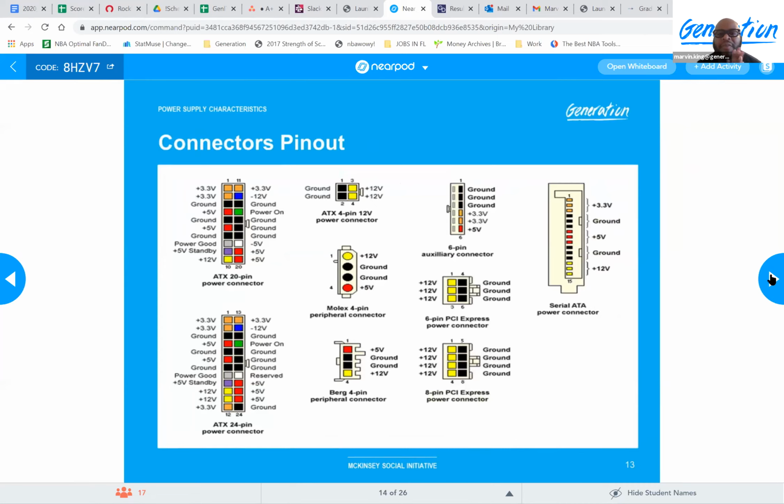And this is a pinout. As you can see, I think this talks more about what Christian was asking and also what Chris pointed out, and why those particular connectors can feed those devices with the same connector. If I buy a hard drive and it has a Molex or a SATA power connector, look at this pinout here. I'm hovering over the Molex 4-pin right here. 12 volt is my yellow and black is my ground. Black is typically my ground.